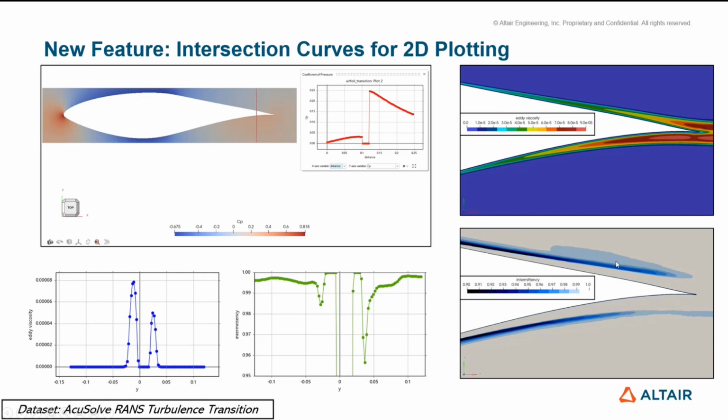And then that's backed up just by a qualitative contour to show that, okay, yep, there is this shear layer happening right near the foil. And our intermittency goes to 1, indicating that the flow is fully turbulent at those locations. And that, of course, matches up with the eddy viscosity that we plot in the wake of the foil.